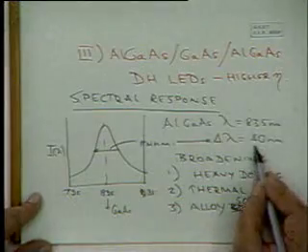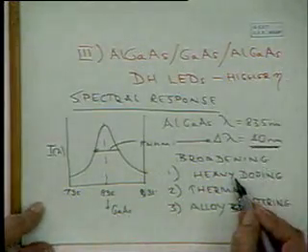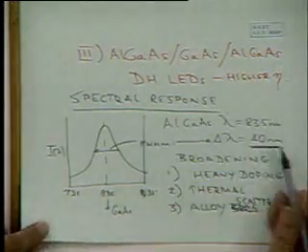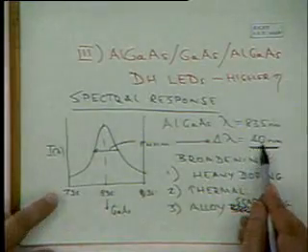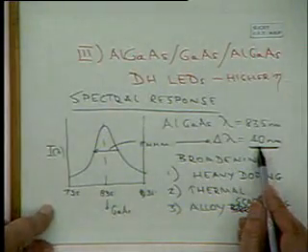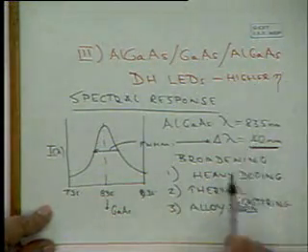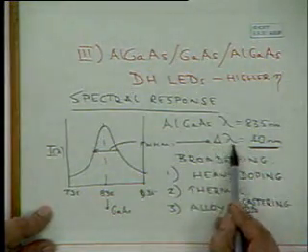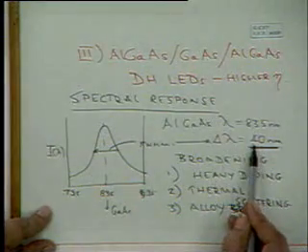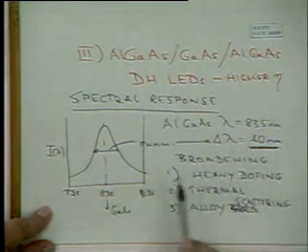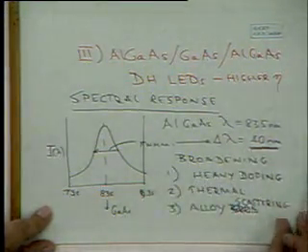So 400 angstroms is a fairly broad spectrum. It's fine for display devices, obviously, but if you want to use these devices for communication, then this is too much, because the different wavelengths will travel with slightly different velocities, and you will get spectral broadening.